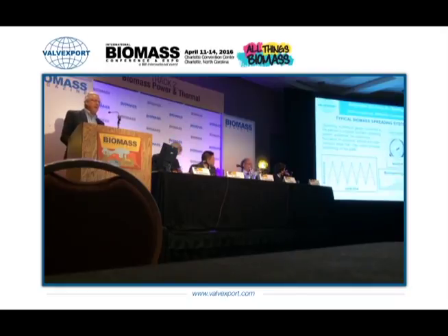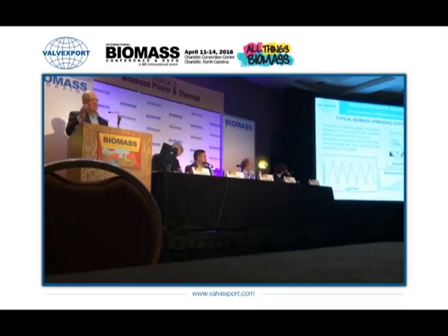If you take a pressure gauge and connect it to the box that sends the air behind the nozzles, in any one of the existing distributors in the market, as far as we've seen them, you will see that it continuously goes back and forth. It does not either step up or down, or stay at one point in particular. So the graph here is what you get.